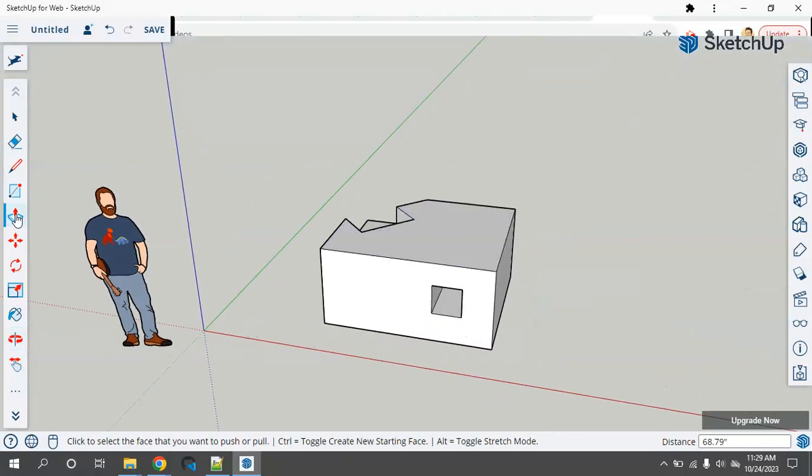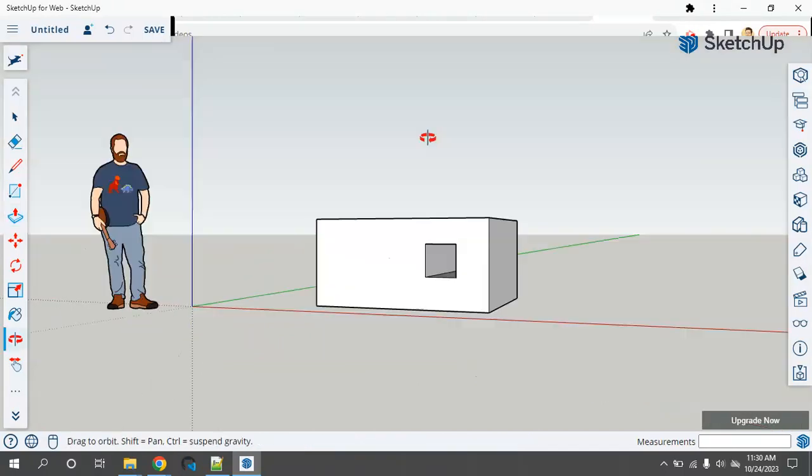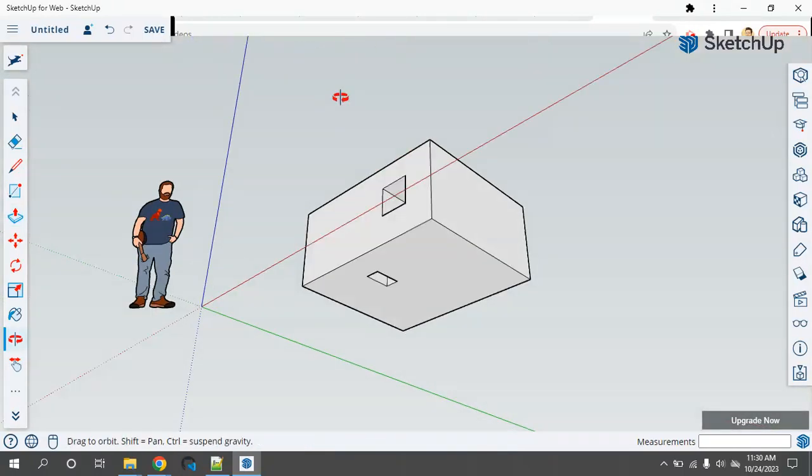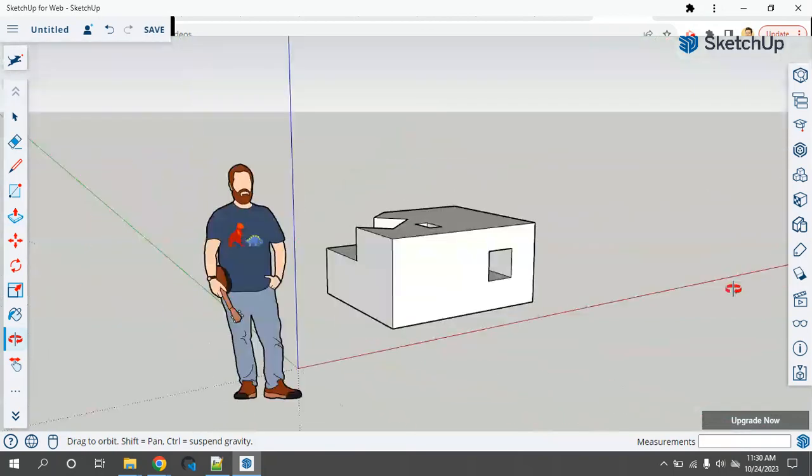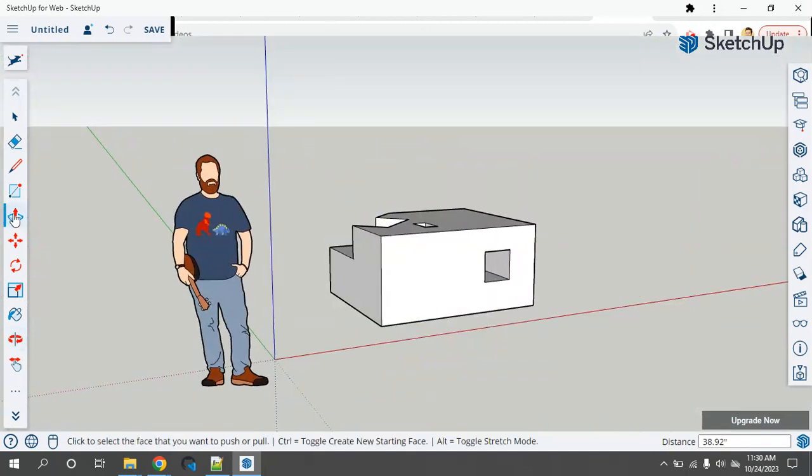So one more time, if I create, say, a little shape here, use my push-pull tool, that will allow me, if I go all the way down, it will snap onto the backside. You can see I could keep on going if I want, but if I snap onto the backside, then I've created a hole. It will delete that face there. Now, one thing you need to be cautious of as you're doing something like this is if you, say, grab that, I'll make a little face there.